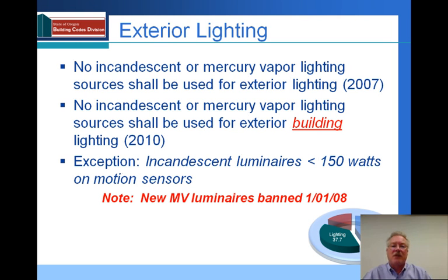It does now clarify a point with regards to incandescent luminaires. Incandescent lighting can be used now for things like landscape lighting, sign lighting, or in fixtures that are 150 watts or less on motion sensors.